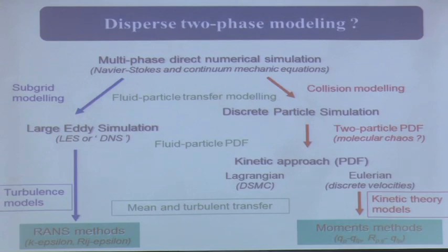What is the benefit of getting wrong answers quickly? It at least helps to start identifying where the open issues are. For example, if you identify that when you do this simulation, this is the part of the system where the code is blowing up, it means you need to understand what is going on there. And it's also because, let's say you make a choice which is very CPU demanding, you think it is maybe the good choice, but you will get the answer in 1 month.